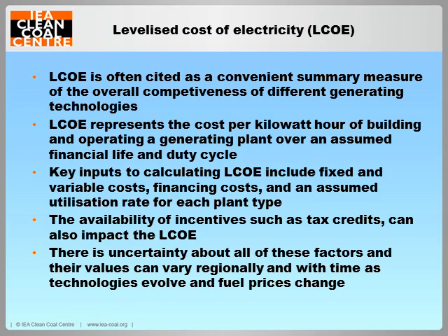The levelized cost of electricity changes in rough proportion to the estimated capital cost of generation capacity. For technologies with significant fuel costs, such as coal, both fuel costs and overnight cost estimates affect the levelized cost of electricity significantly. Overnight cost is a terminology used frequently to describe power plants. It's the cost of constructing a project if no interest was incurred during construction, as if the project was completed overnight.